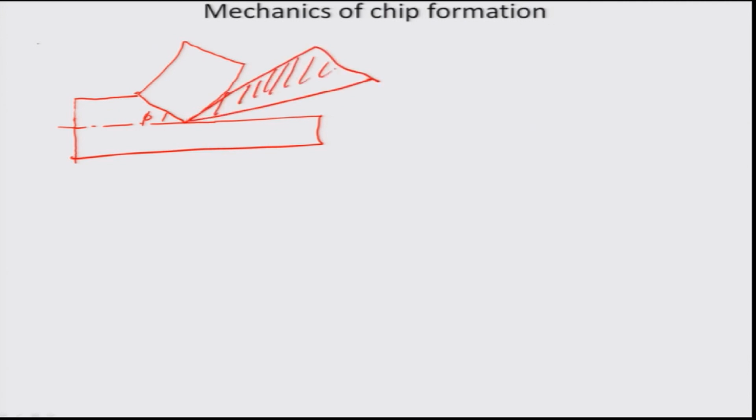So this right here is the rake angle and phi, and this is the remaining portion of the cut surface. This right here is the tool. So we are making a clearance angle on the tool on one side and the rake angle on the other side. So having said that, now we want to really find out what is going to be the total shear strain that is needed to do this chipping action that is going to take place. So let us call this point S as usual,